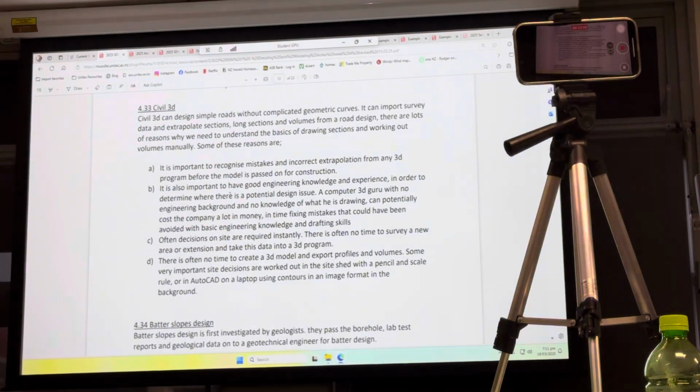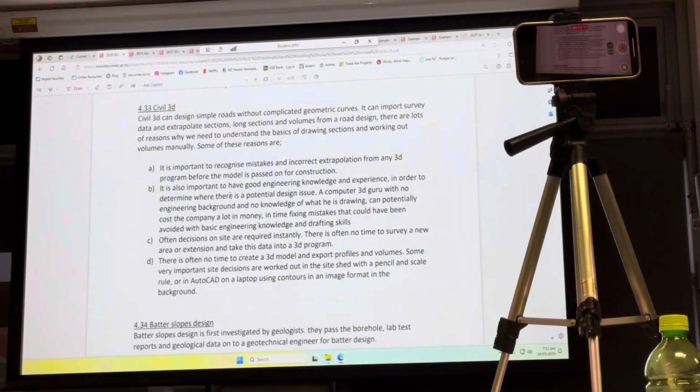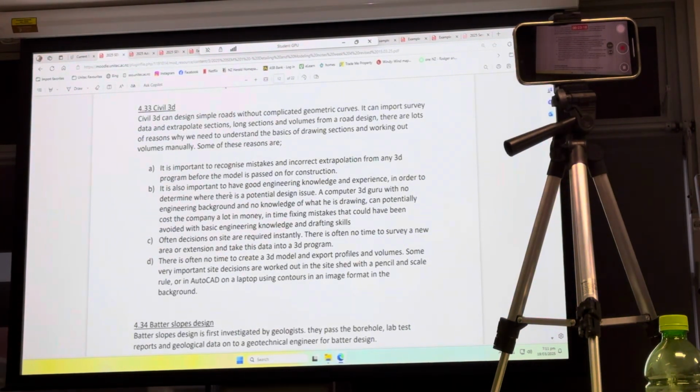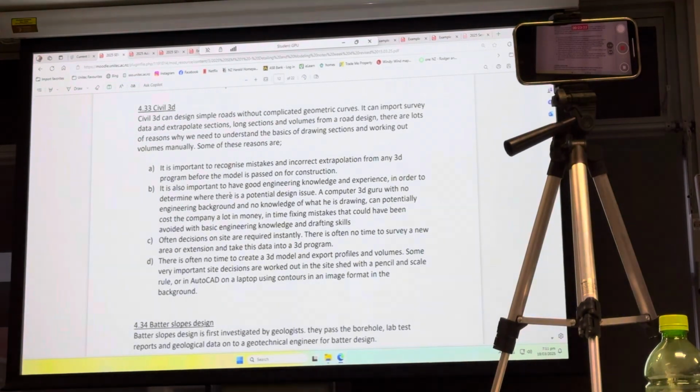Now, I have included a couple of points that may not be correct, so you will need to go through just to make sure that, when you're doing your points, you may need to delete a couple. Just go through and have a look to see. Remember what it looked like, a little volcano? If you see any of those, it's the wrong one, and it will be obvious. It'll be a peak or a trough where the surveyors put the wrong point in.